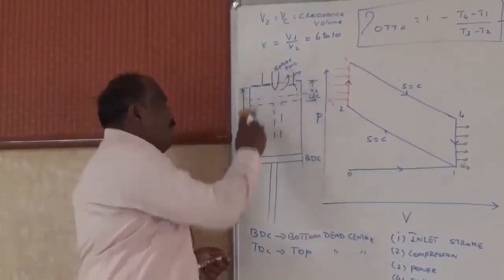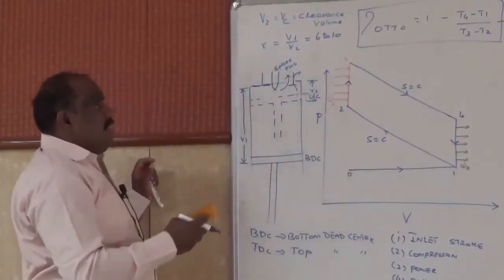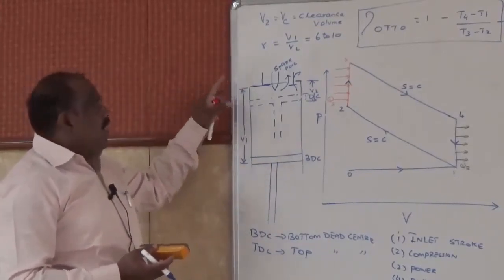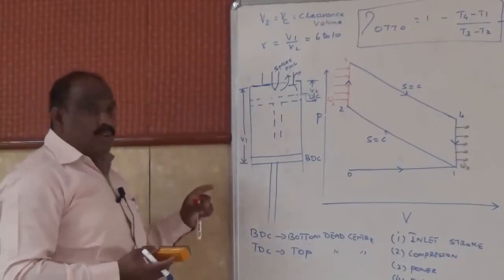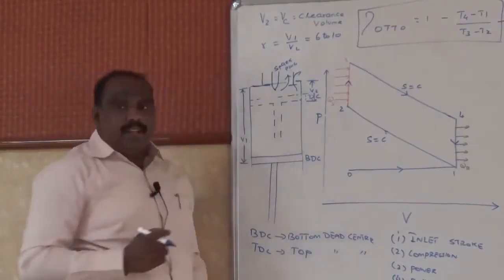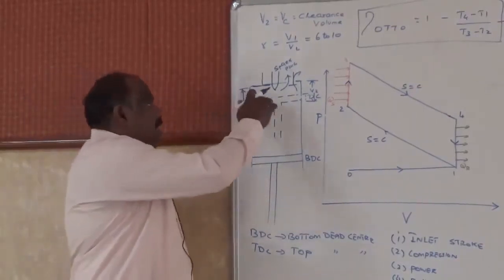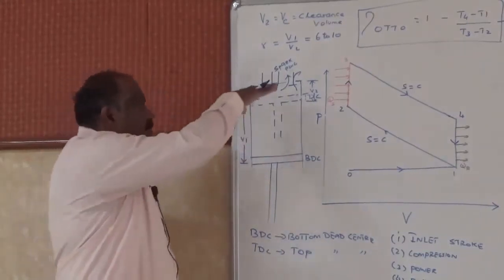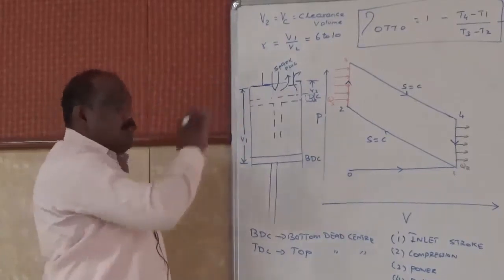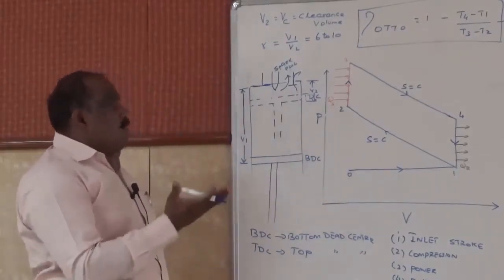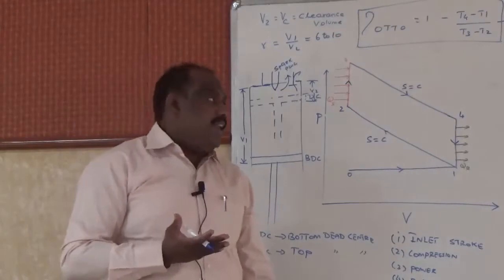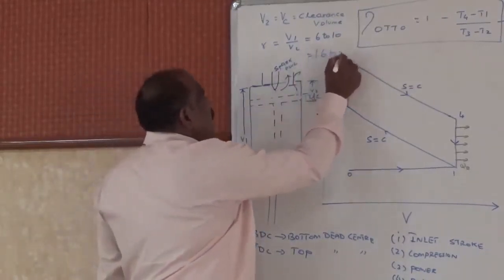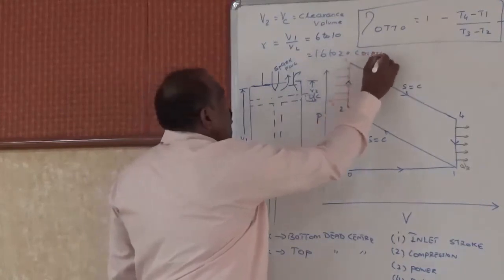And coming to the diesel engine, the only difference is during the suction stroke, it is not petrol and air, or diesel and air, that come in. Only the air will be entering into the combustion chamber, and there is no need of any carburetor. The piston once again moves from the TDC to BDC. The exhaust valve remains closed. During the compression process, only the air gets compressed, whereas the compression ratio will vary from 16 to 20 for a diesel engine.